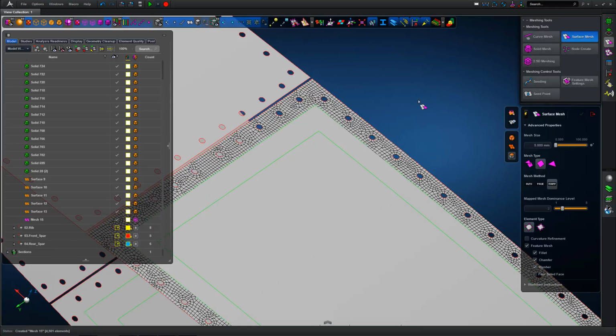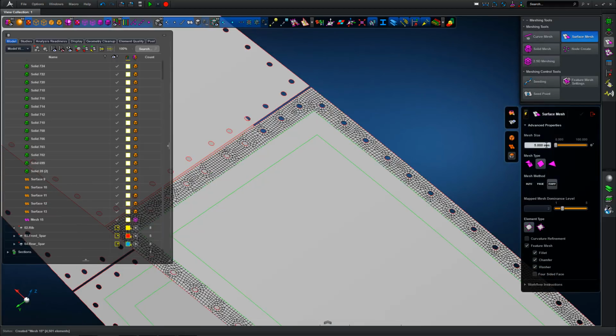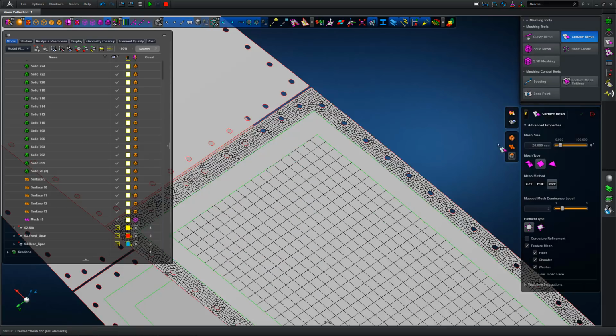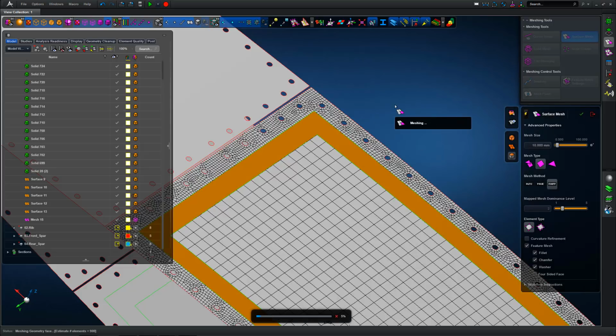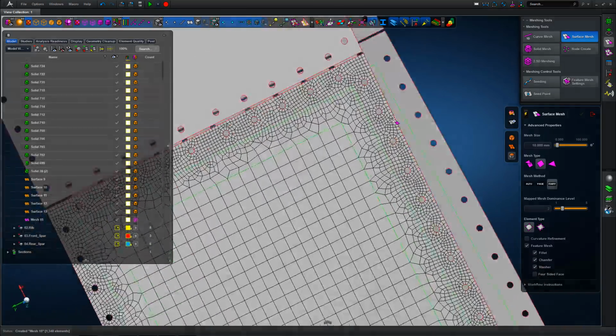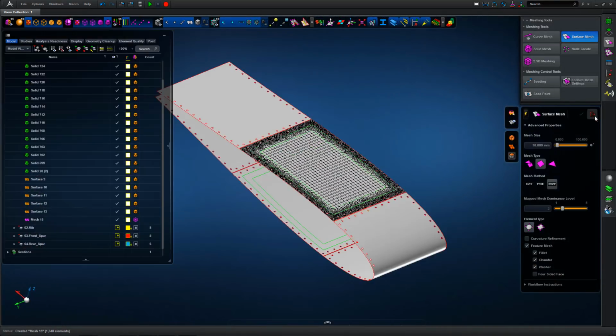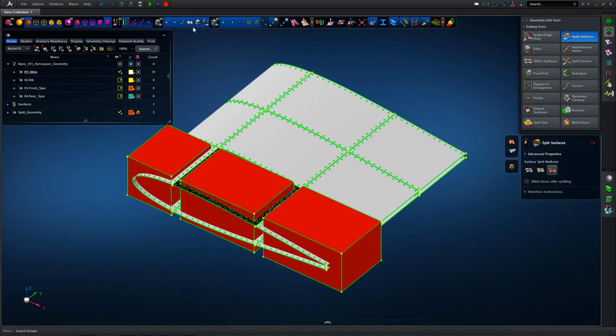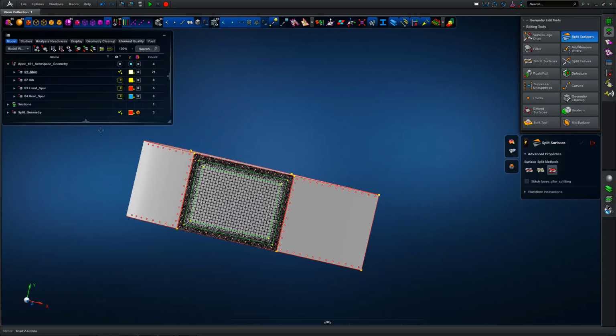So we remesh the fine region with a 5mm edge length, a quad only mesh. If you were to focus on the holes, you can see there's the washers with the nice regular washer definition defined. We can mesh the coarse region with a 20mm edge length, and then the transition region with a 10mm edge length to transition from fine mesh detail where we need it around the fasteners, but to coarse elsewhere, still maintaining good element quality and minimizing the overall size of the model.